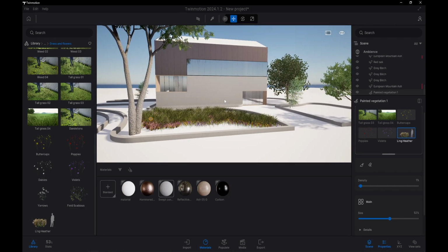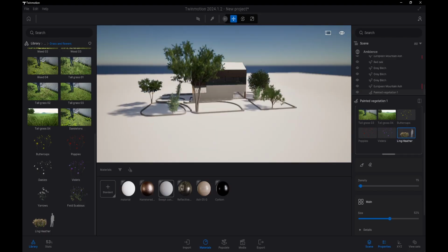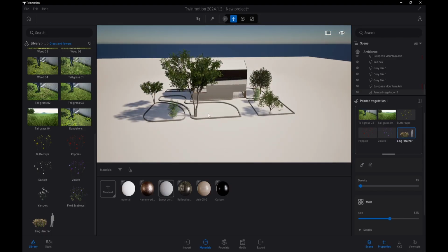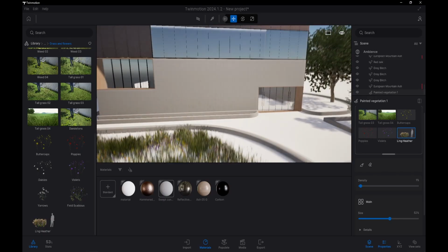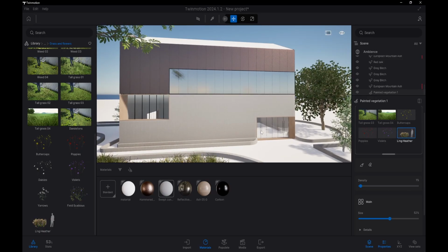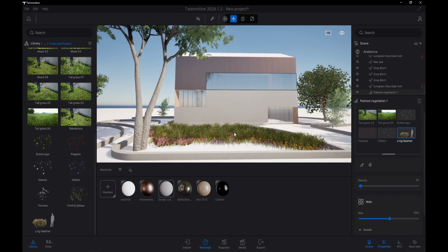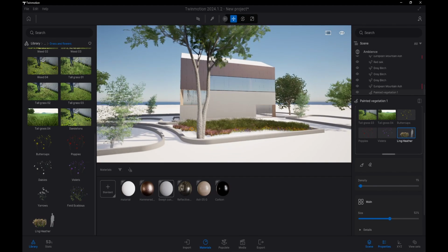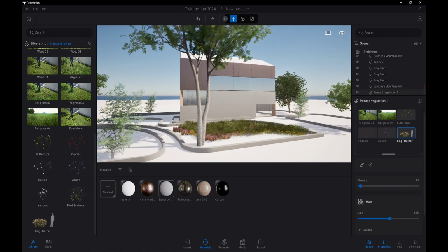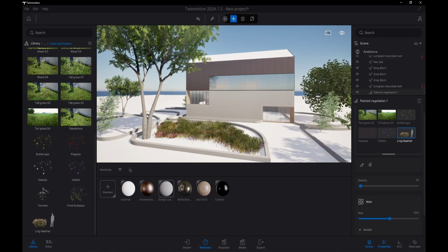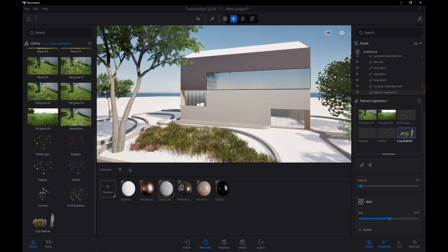And so Twinmotion has these settings where when you're more zoomed out, it's going to delete the preview image of your landscaping. But the more you zoom in, it'll come back. So don't worry about that. Also, these settings for the reflection aren't even the best. I have this in mediocre settings, and I'll show you what to do with the actual settings of the actual lighting and the reflection and the render settings. So don't worry about that. I'm just trying to cover all of the major necessities, you know?